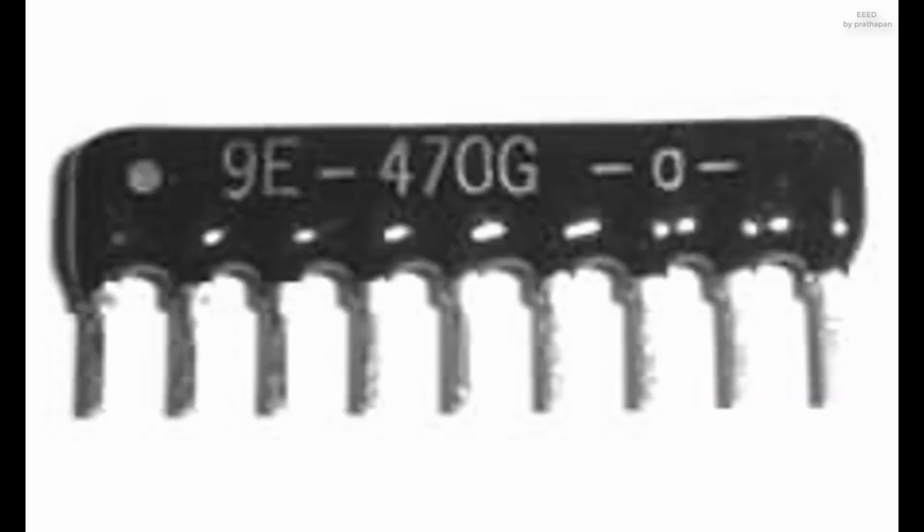Fixed resistor. A single in-line, SIL, resistor package with 8 individual 47 ohm resistors. This package is also known as a SIP9. One end of each resistor is connected to a separate pin and the other ends are all connected together to the remaining, common, pin 1, at the end identified by the white dot.